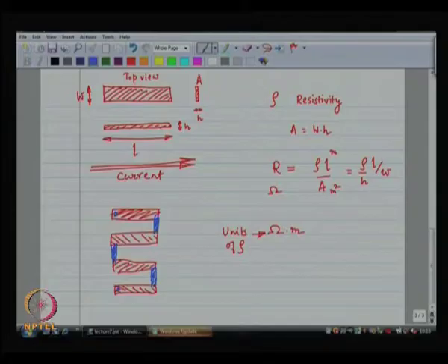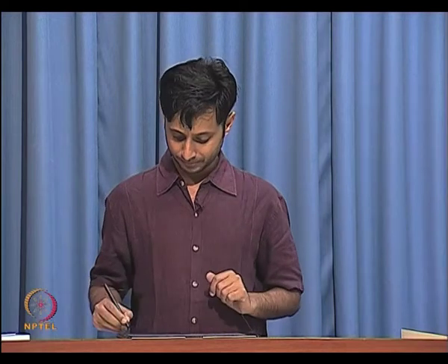If you draw it like this, it is also easy to ratio two resistors. So, if you want R and you want 5 by 4 R, then all you have to do is split R into 4 pieces like I have done for resistor number 1, and for resistor number 2 you use the same piece and make 5 pieces. So, you have resistor R and 5 by 4 times the resistor.